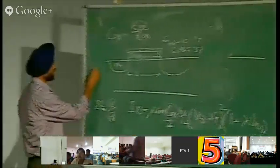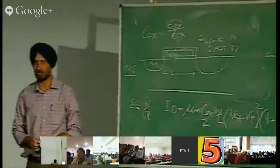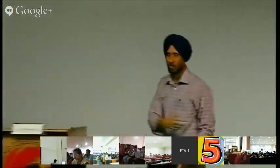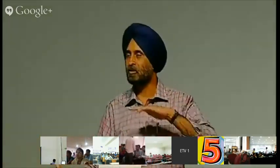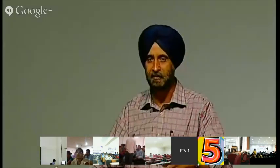This is the concept. So below 45 nanometers, silicon dioxide cannot be used. A lot of research is going on. There are around 5-6 materials. Hafnium oxide currently is being used. There are some other materials, tantalum oxide, and others also. Because Cox has to be increased. That is the purpose. Now you will ask why Cox capacitance has to be increased.